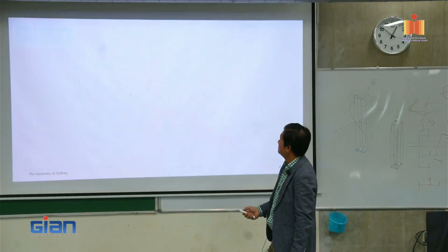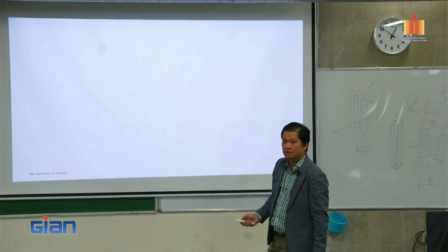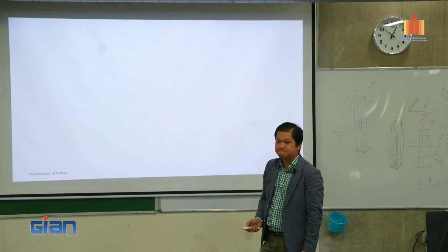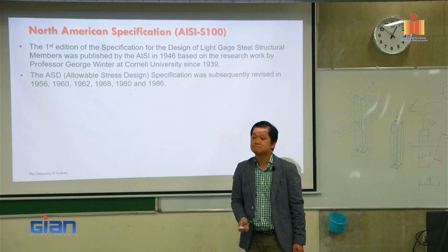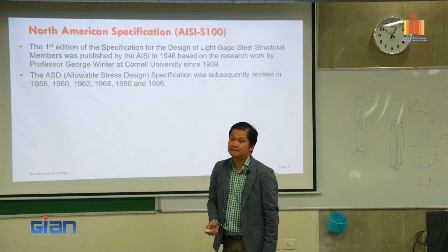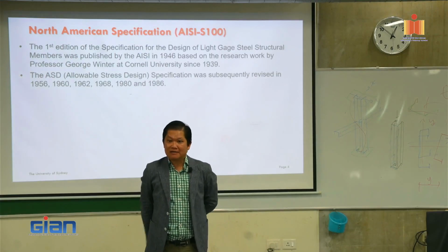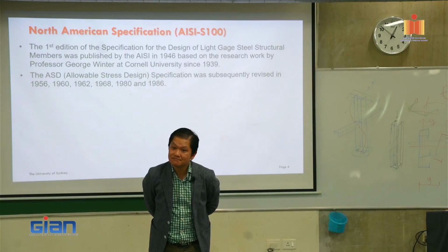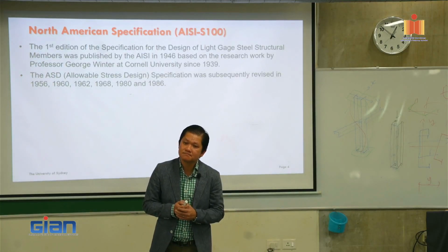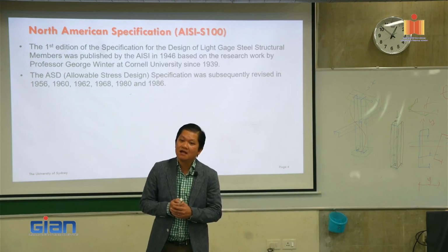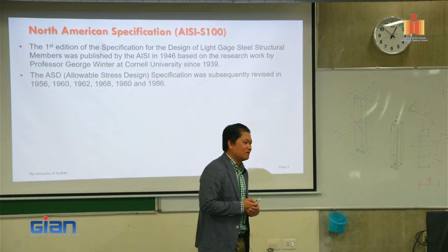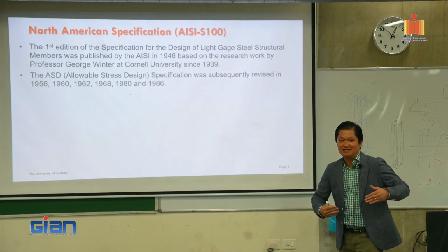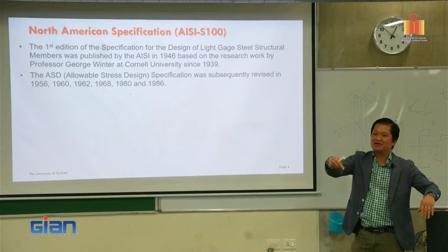Okay. The example in the beam, you have taken the example of purlin. Actually, purlin is an asymmetric building. The purlin that we choose here is a C section, a singly symmetric section. I'm specifying the direction of load applied on the section. So we assume that it's the wind uplift, so it's perpendicular to the section.